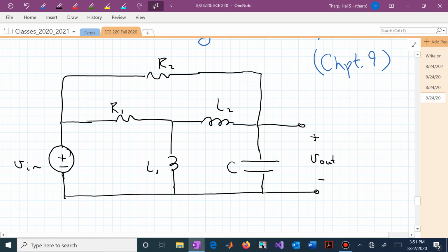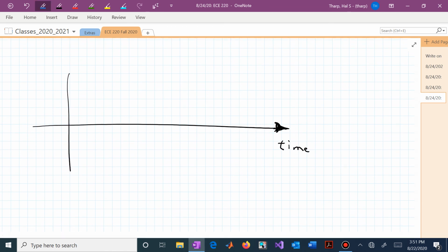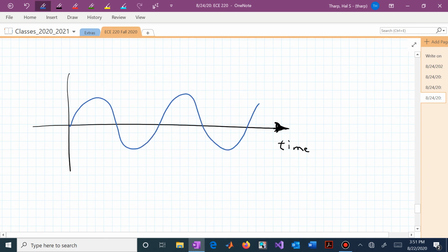If it's a third order, fourth order system, we are going to now restrict our input sources to being sinusoids. Let's say that it's the same positive as it is negative. We will now assume this is in sinusoidal steady state, which means that this sinusoidal input voltage, Vn, has been in existence for a long time until we've reached a steady state.